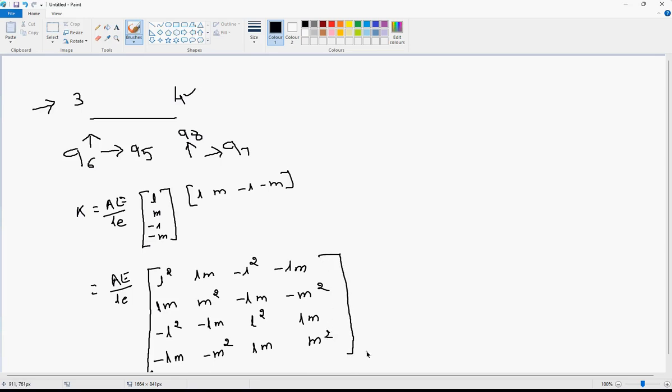Okay. So this matrix I have to remember because I need to calculate cos and sine of each element. Okay, and then we have to prepare this one. And now how will this be there? So let us say if I have a 3 and 4, okay, so I have to multiply by 2, so I get 5, 6, okay, and if I have a 4, I will get a 7, 8, okay. So my column and row heading will be 5, 6, 7, 8, 5, 6, 7, 8. So at this location, these elements should be added. That I have to remember.